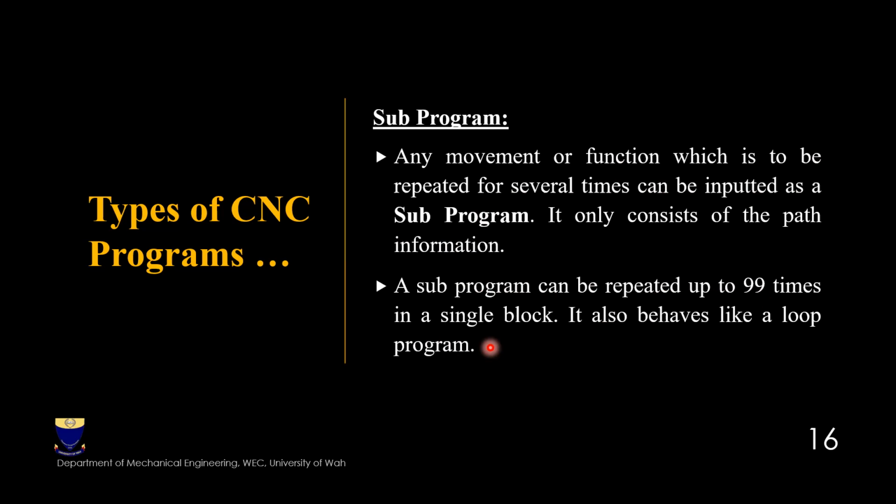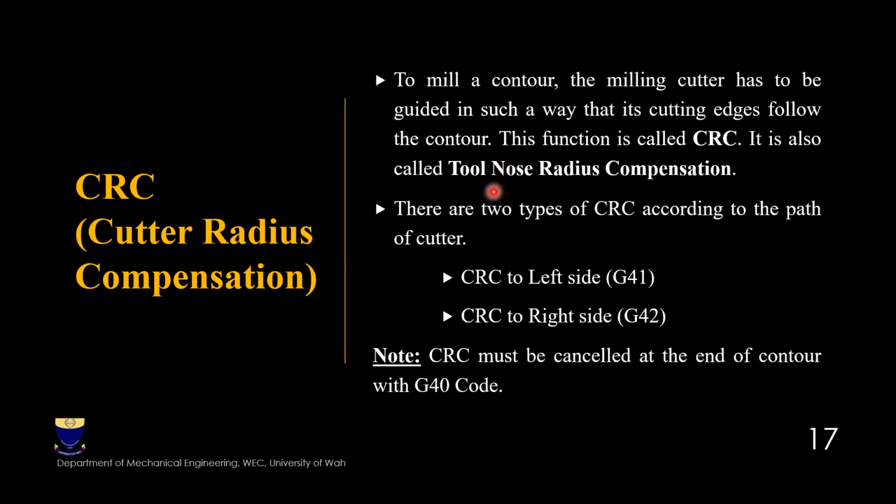So all these programs act like a loop. You cut a depth of cut of 0.5, then 1, then 1.5, then 2, and so on, whatever is required. Or a depth of cut of 0.01 or 0.1 can also be done if you have to. That is where a subprogram is used.